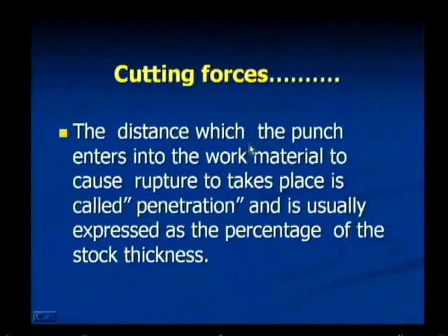The distance which the punch enters into the work material to cause rupture is called penetration, and is usually expressed as a percentage of the stock thickness. So, this penetration is the distance which the punch moves downwards for failure or cutting action to take place.